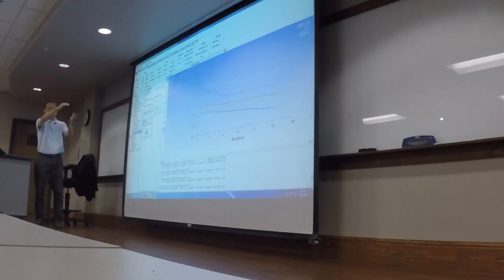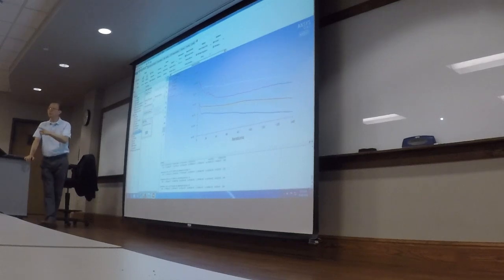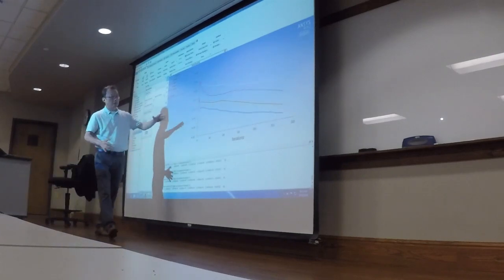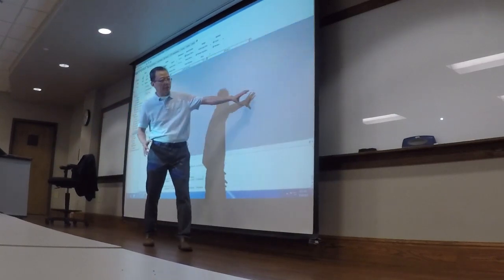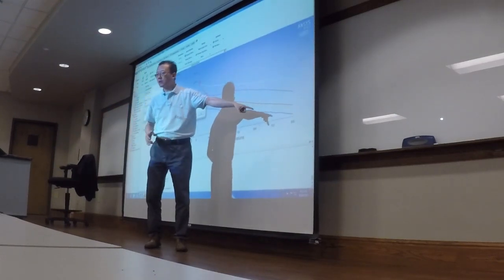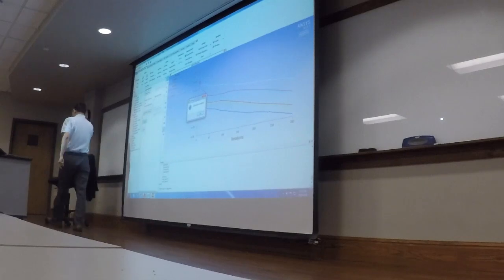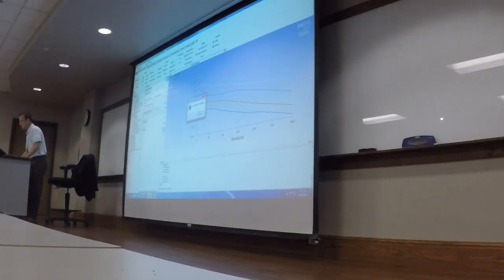All the residuals are going down. What I'd like to see from your homework one is I want to see all these lines level off. Which means, see, this is still running. 300 is not enough, so let's make it 300 more maybe.